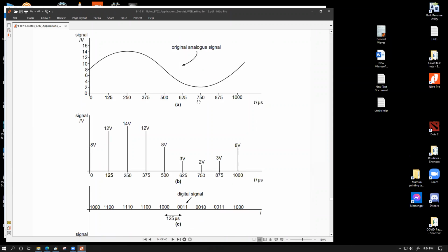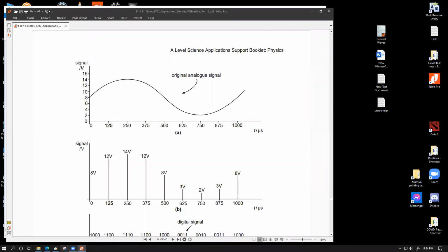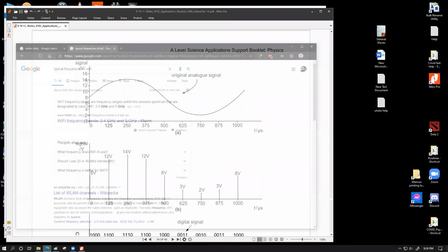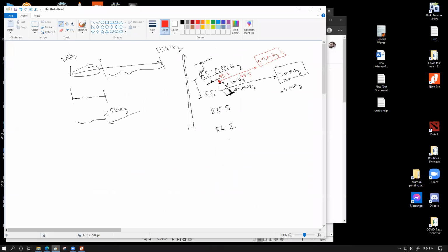For these examples, we have used a sampling frequency equals to 8 kilohertz. I'm going to write this up over here. 8 kilohertz means we're going to look at the original analog signal 8,000 times every second and pick up the instantaneous voltage value of those instances.